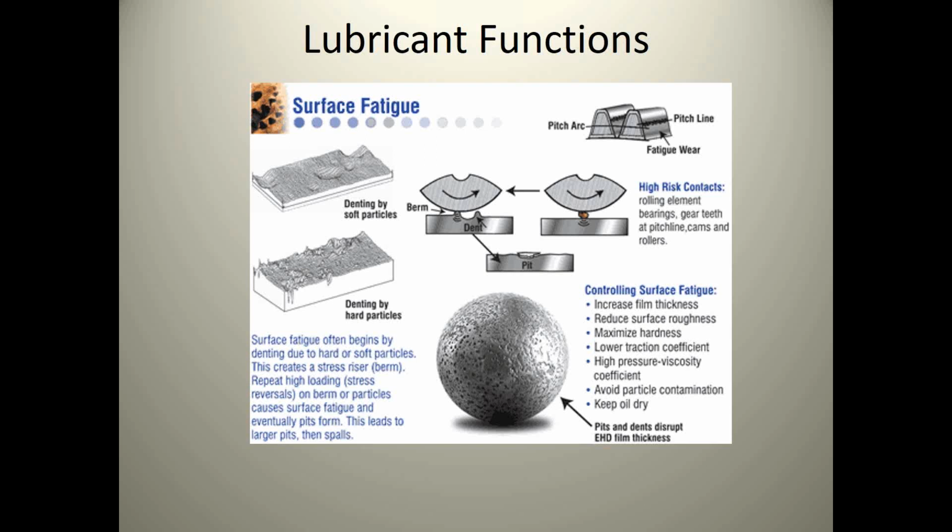I attended a Timken bearing class many years ago, and what they were telling me is that underneath the loaded part of a bearing or a gear, you can develop 20,000 psi of hydraulic pressure, and that's enough hydraulic pressure to do a lot of damage to your surfaces, just hydraulic pressure alone.